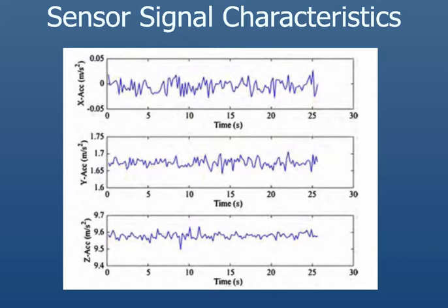This has to do with the so-called aliasing effect that can seriously undermine any digital signal processing system if it is not properly sampled. In general, aliasing occurs if the bandwidth of the analog signal that is being sampled by the system at discrete intervals exceeds the so-called Nyquist frequency.